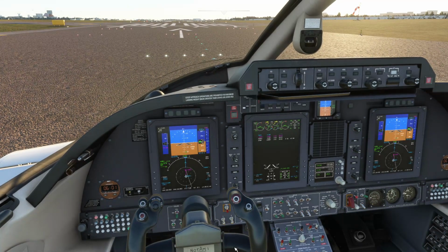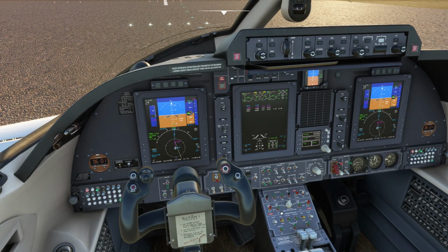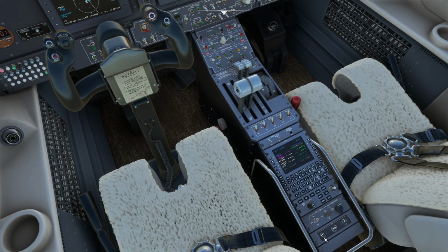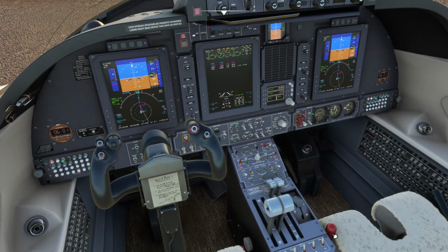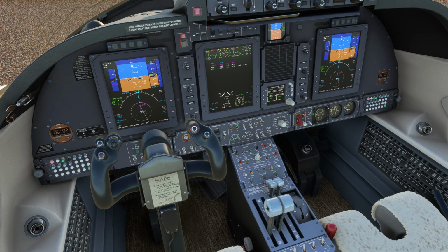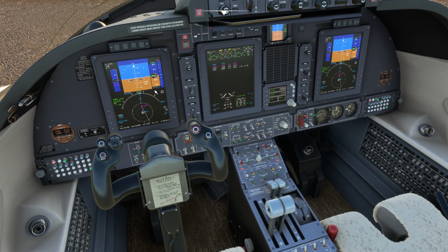Fuel pumps, obviously. These are on main, these are here. Condition levers, again, check. Flaps, check, and they match the handle. Pitch trim is set, rudder check. Flight controls, any resistance, nothing. Everything is fine. Steering is going to change automatically, so keep an eye on that. I won't be making comments when I'll be taking off, but keep an eye on that message here. And oil coolers are not needed.